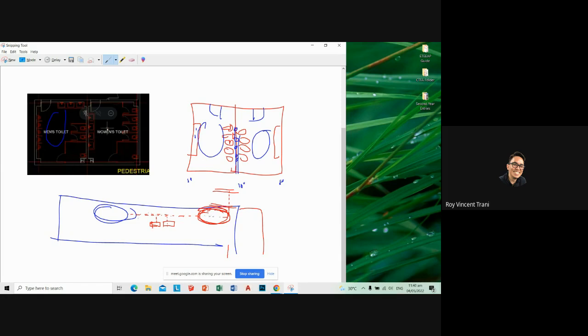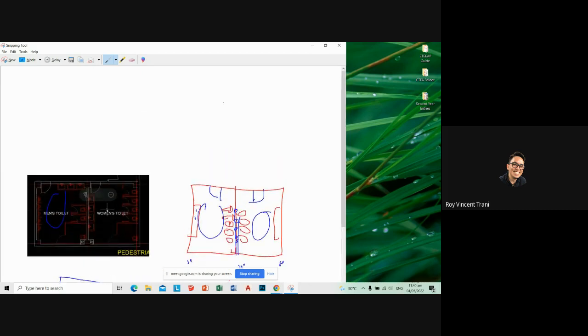And usually you would put them in a way that they don't bump into or interfere with normal traffic. It's biased toward normal people, the non-visually impaired. So for example, this is a hallway. You can choose either side. So the tactile pavement would be here, so they can go this way, and then the normal pavement would be here so that the pedestrian can go this way. So you don't want them intersecting as much as possible.